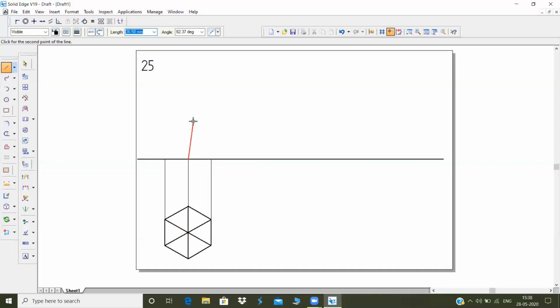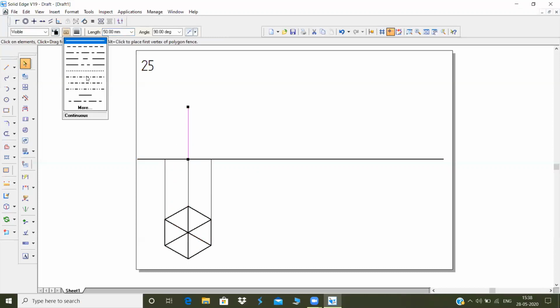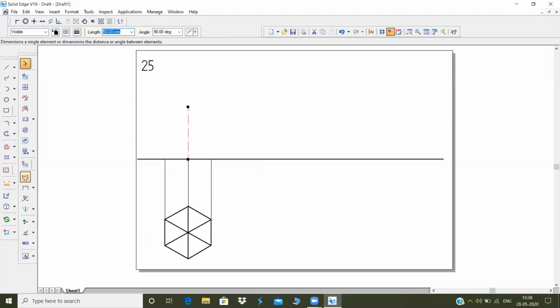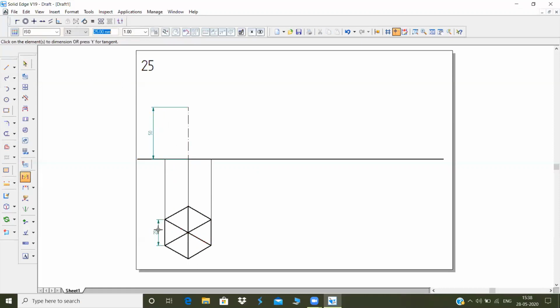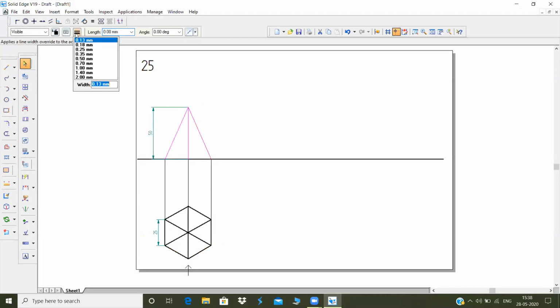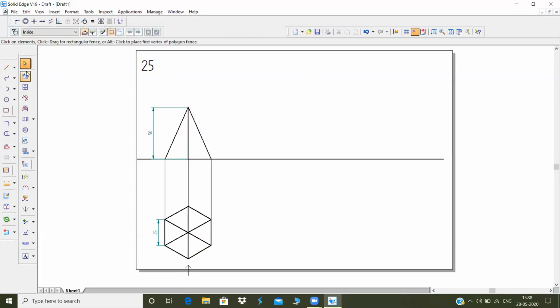Okay, so it is given that axis is 50 mm height here. So first you have to take the axis height. I have told you many times in the previous also, that you have to first draw the axis line. So this is 50 mm. Okay, and you have to join this from the ends. Now since it is resting on edges, and when you are seeing this from this side, this edge will be visible, so the axis will not be visible to you here. So all the things will be thick lines itself. I hope you're understanding this.